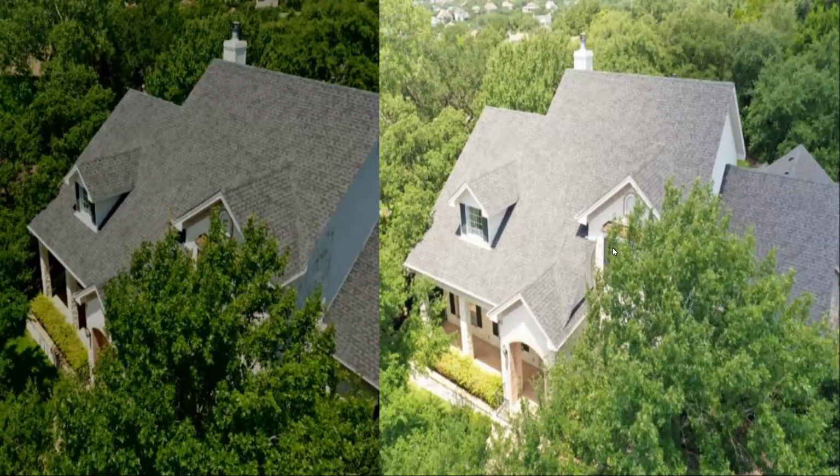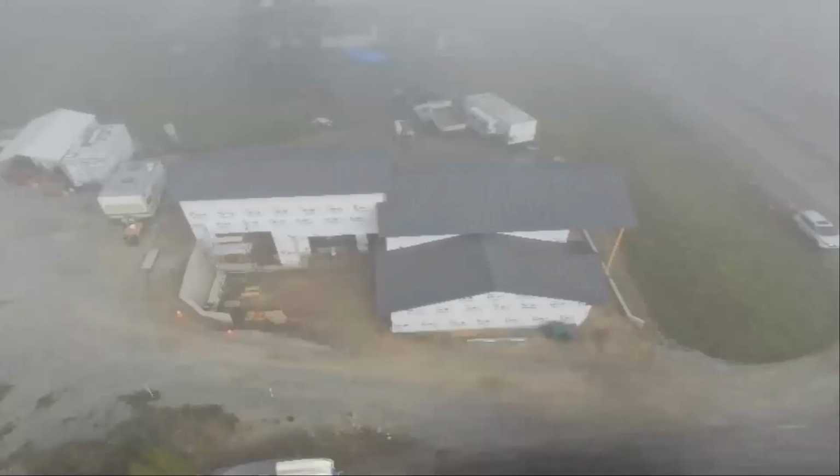Okay. And then finally, images taken when the drone is flying too fast or foggy weather or really dark conditions can create blurry images. And this diminished clarity will cause site features to not map so well, right? So these are the types of images that we're trying to avoid, and this is what we want to help you perfect and clarify, all right?